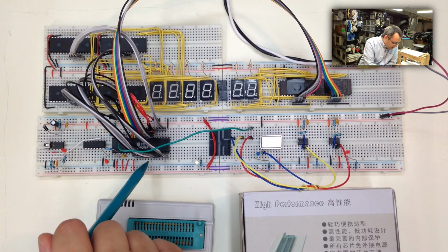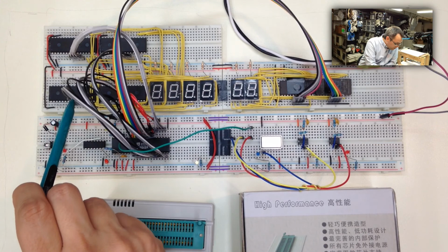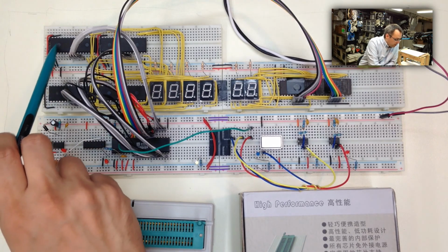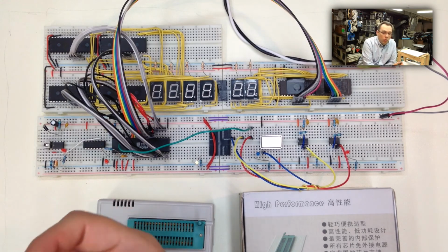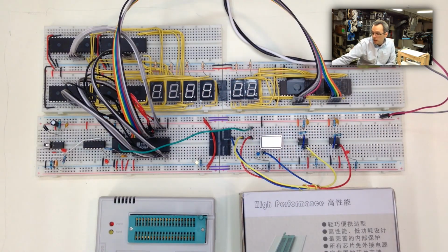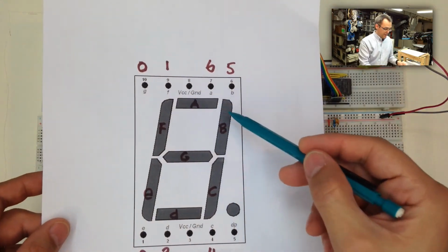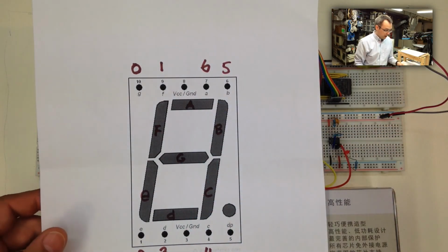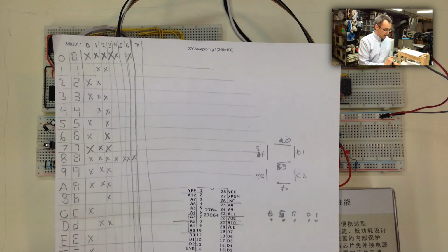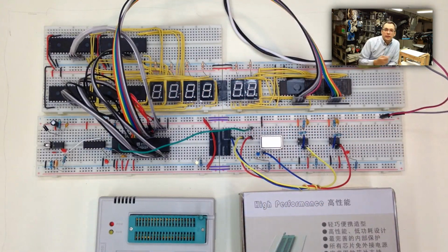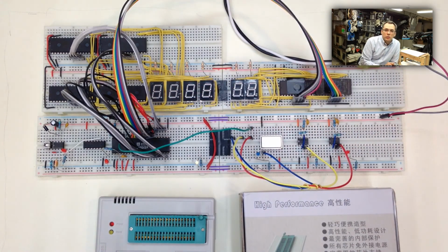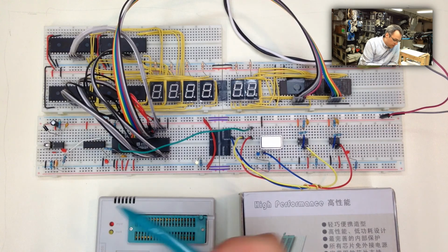So basically what happens is, when any 4 bits of the address bus come out, it's going to select 0 through 15. The value 0 through 15 is the memory address for each one of those chips, and in 0 through 15, I have the value I want. Location 0 has the byte value that corresponds to the lights, which in this case would be A, B, C, D, E, F, in order like that. In the truth table here, A, B, C, D, E, F, skipping these other lights we don't need, and it would just light those bits up. Then 1 would have these 2 in those byte values, then 2 would be those, and it would just do that. Set it up all across, wire it up, hook it up, and it just works.